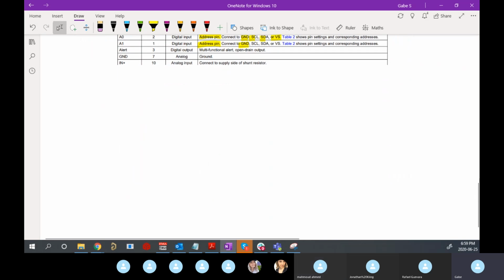In part, it's because it's synchronous, but it's mostly because of the half duplex nature. There's only one data line, and that has to be shared amongst everyone. So only one communication can happen at a time. More than one person can't send data at the same time. Otherwise, it's going to cause conflicts and create garbage on the bus.